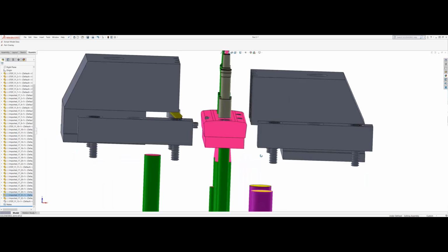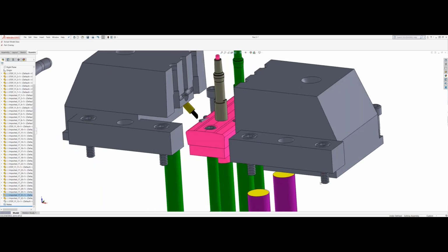Did you need to cool the core pins to dissipate some heat? We did not. There aren't any cooling lines directly at the core pins. There's not really enough room in the tool to add in any kind of cooling system through there. We put pretty simple cooling lines through the frames, that John said are proprietary bases, and we generally just cool the entire mold all at once.